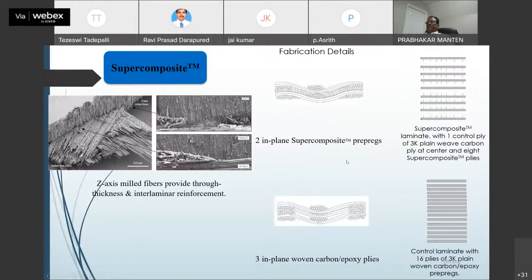What is that? A company called Boston Materials here in the US has developed a material in which, between two layers of carbon fibers, they introduced what are called Z-axis milled fibers. These are very effective in trying to reduce the shear effect which takes place in composites. Most of them get shear and delamination, one of the dangerous modes. So by growing them on top of this, they introduce them. We wanted to test those to see what effect those laminates have, apart from their modulus or anything.